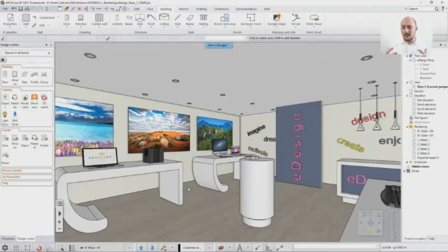And when you start rendering, the first thing that you need to set up properly, besides the lighting, is the materials themselves. So to be able to do that, you need to remove things that are not necessary now. All the tiny details are not necessary. We are looking for the large surfaces, for the wall, the ceiling, and the floor. And this is what I would like to see. So for that, I will use the layer system of the software.